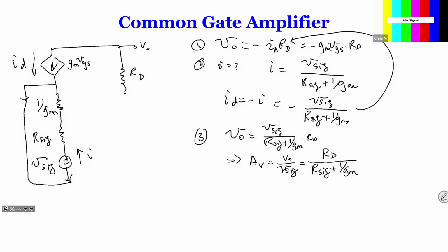So in this, you can see why the T-model is simpler in this case, because we didn't involve vgs at all. So we simply find the current, because what we wanted is to find the ratio. Once you have the ratio, let's say input is 5 millivolts and your ratio is 100, and the output is like 2500 millivolts, right? So that's how you can get really just very simplified circuit.